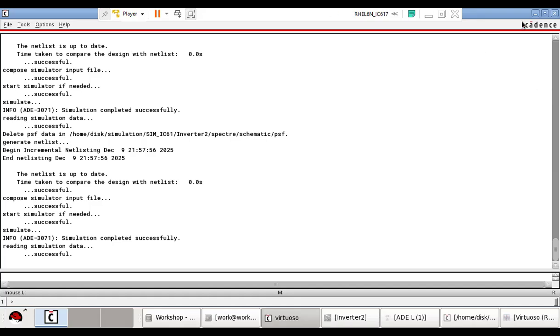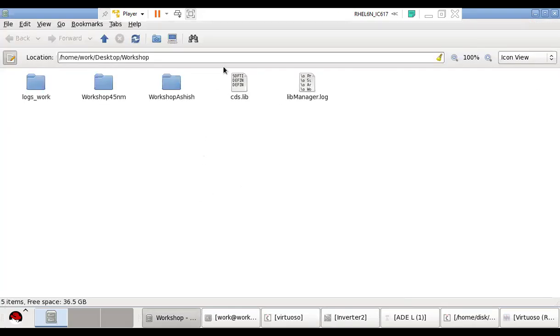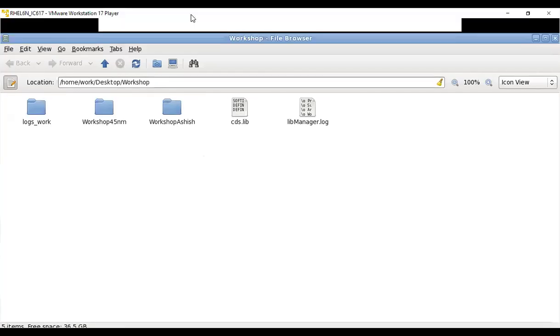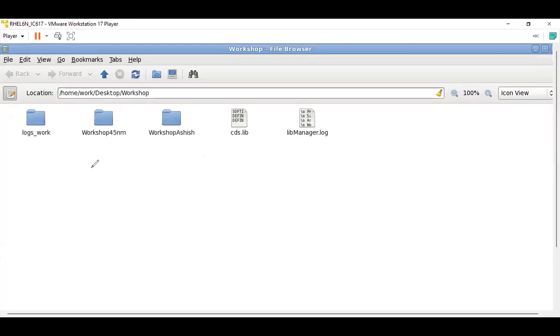If you have any question, you can stop me anywhere, because this is a very important part. Even if you know everything about your device and your circuit, if you have not done these process corner or Monte Carlo simulations, your results remain incomplete always.